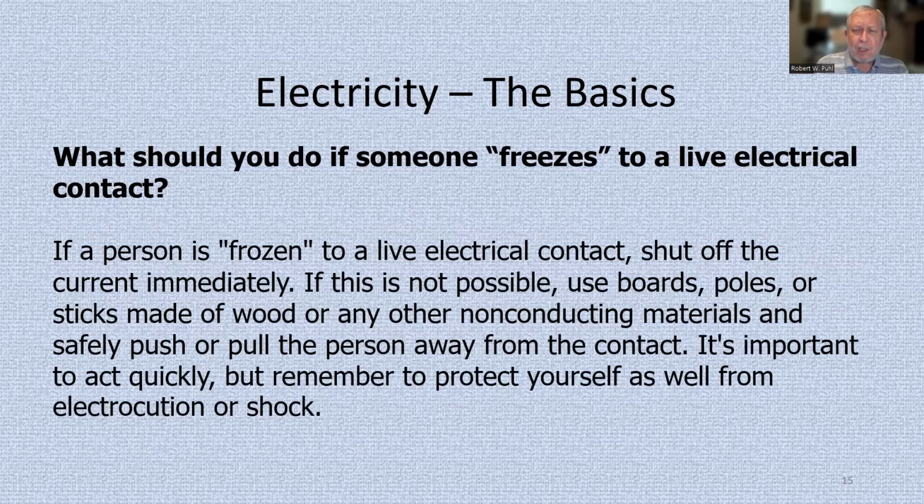What should you do if someone freezes to a live electrical contact? If a person is frozen to a live electrical contact, shut off the current immediately. That's the first thing you want to do. If that's not possible, use boards, poles, or sticks made of wood or any other non-conducting materials and safely push or pull the person away from the contact. It's important to act quickly, but remember to protect yourself as well from electrocution or shock.